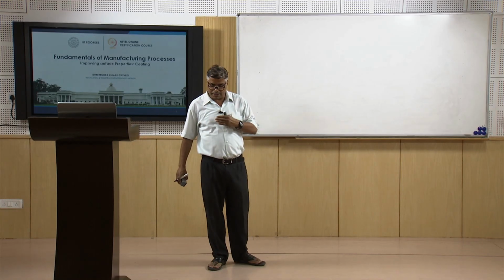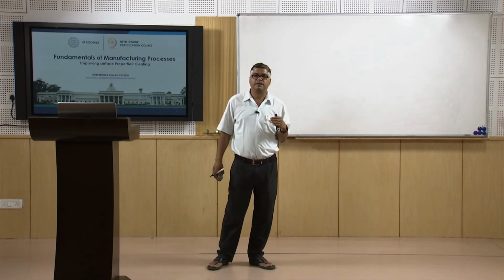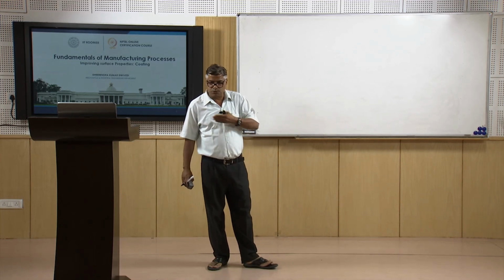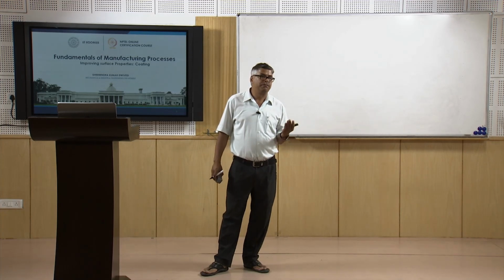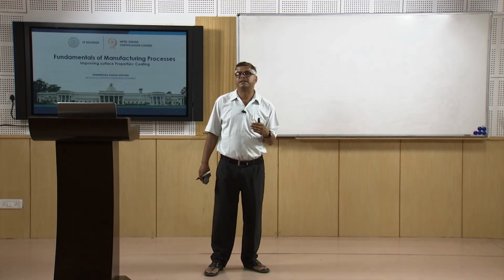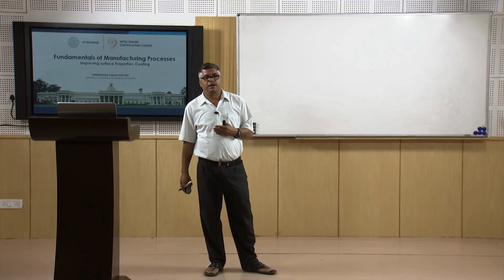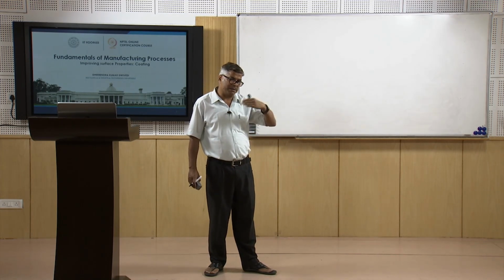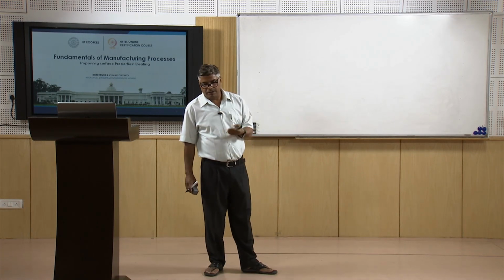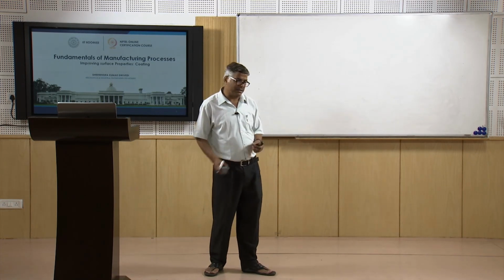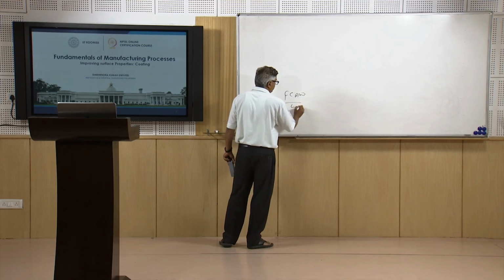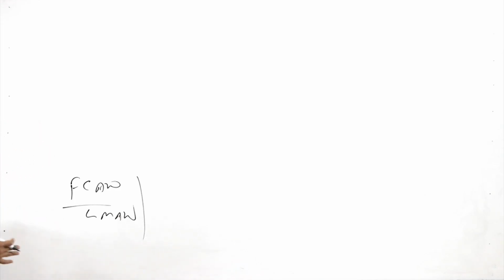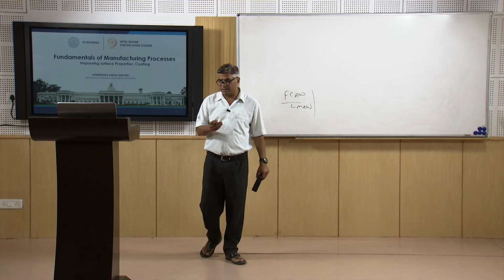Submerged arc welding is used when a very large area is to be deposited in large quantity, while GTAW, gas tungsten arc welding, is used when high quality weld surfacing is to be done with less heat input. For general purpose weld surfacing, shielded metal arc welding is carried out, while for specific industrial applications, processes like FCAW and GMAW can be used.